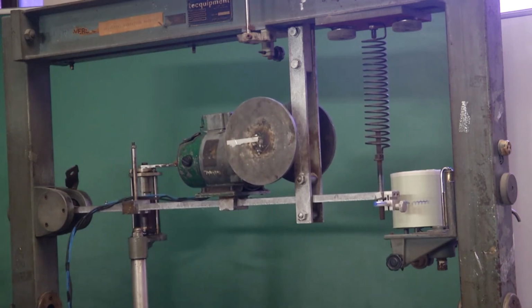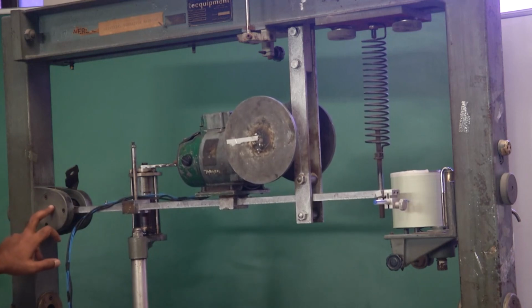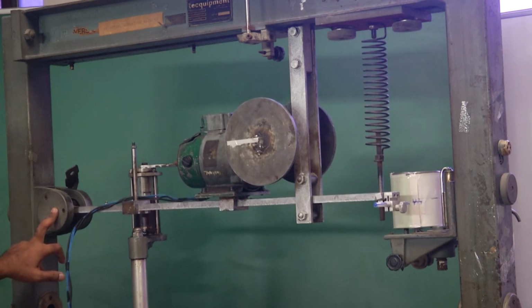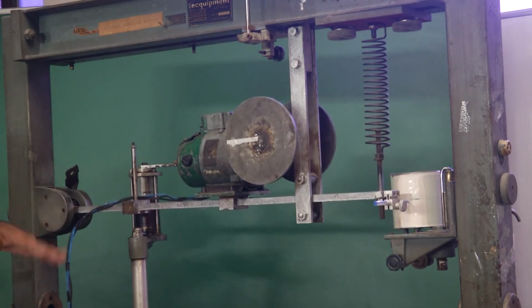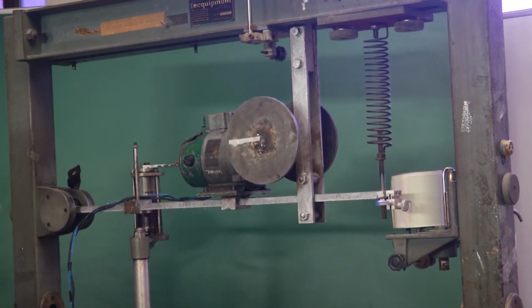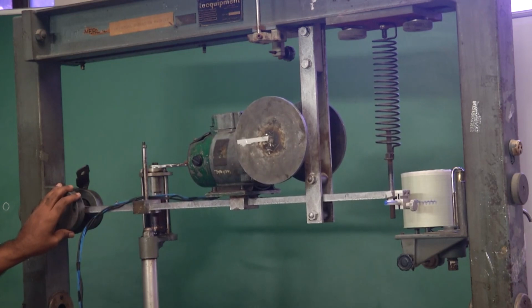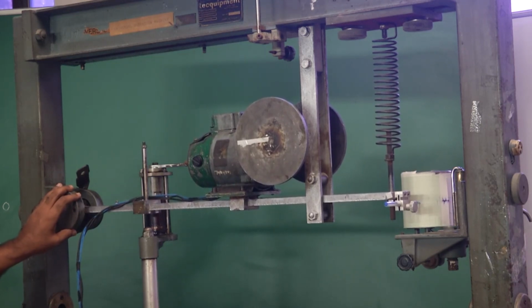The other possibility is the hinge, because the hinge is in the form of a bearing. At the bearing again, because of the relative motion, there is likelihood of some energy getting dissipated. So, the friction at the bearing location, however small, is going to create a dissipation force or damping, causing conversion of the vibration energy into heat.